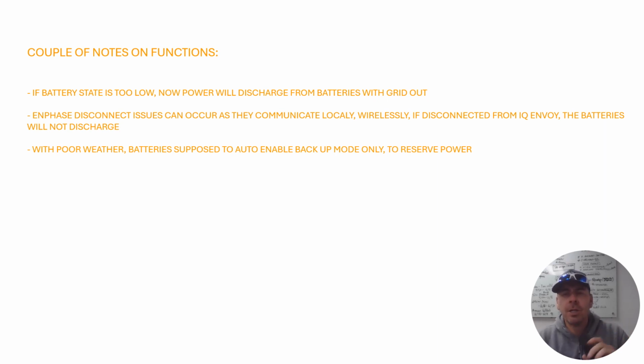So there is a shut-off and cutoff point. Like NeoVolta has a 20% cutoff point. I think Enphase and Tesla show 0, but it's really still 10 to 20% of battery state of charge in there. They just cap it and stop, and they don't discharge power anymore, to make sure the battery is able to recharge itself again and that they can ensure your warranty for the life of the battery. And so that's just not going to happen.